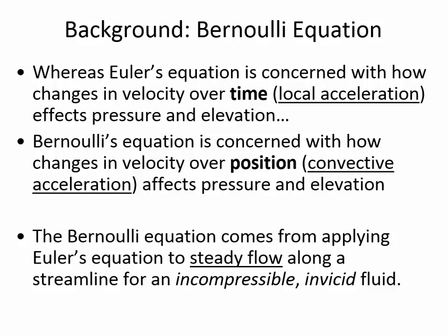But so what this means is that we're going to have some mistakes if we apply Bernoulli's equation to gases that are experiencing compression as they flow. And so a section like this where the diameter is changing could cause a change in the pressure because of the molecules getting closer together, rather than just a change in pressure we'd expect from the Bernoulli effect itself.